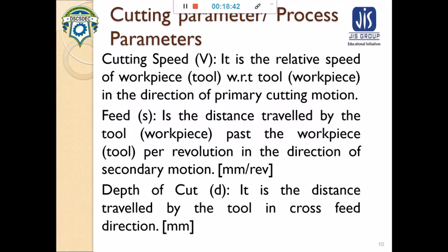Similarly, feed is the distance travelled by the tool past the workpiece per revolution in the direction of secondary motion. And depth of cut is the distance travelled by the tool in a cross feed direction. It is known as depth of cut.